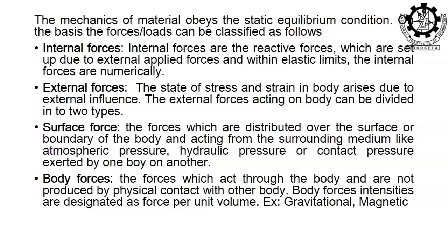If any force is throughout the volume, as it has been written, gravitational and magnetic, if the force acting on a body is gravitational, magnetic, electrical, that means it is acting throughout the body or throughout the volume. If the force acting on a body throughout the volume, it is called body force, it is within the body. Any mechanical forces, pressure, external force, hydraulic force, atmospheric pressure, it is on the surface only. So, it is surface forces.